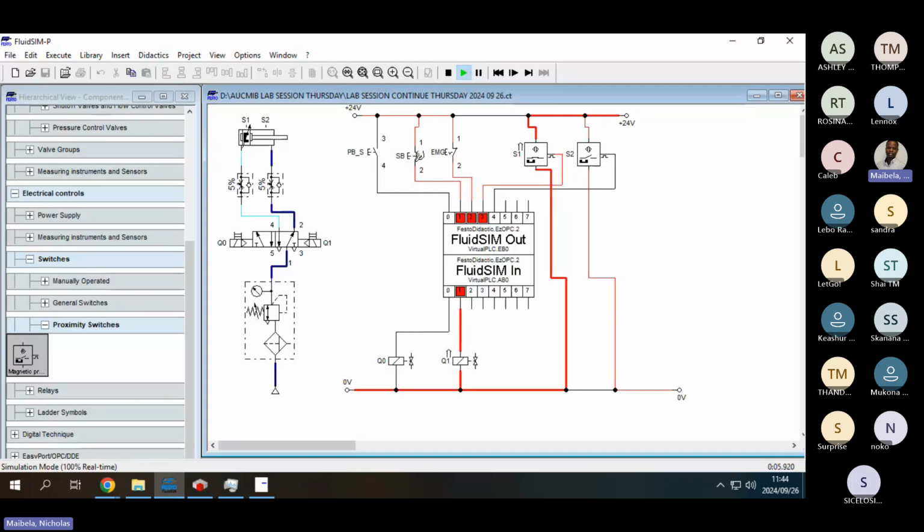If you look at the stop button and your emergency stop button, they are red, meaning they're on. Meaning on ladder logic, you'll normally use your normal contacts without negation. And if you look at S1, it's in a bold dark red, meaning it's on, right? But S2 can be deceiving. You might think it's on, but it's not actually sensed. There's no current flowing through it, even though you see this light red color.